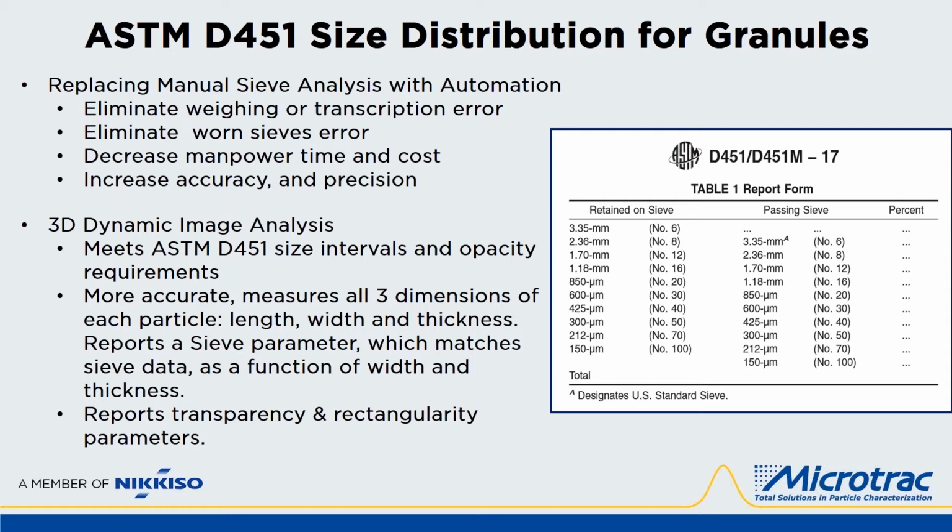Sieve analysis for particle size process control has been replaced by newer automated analysis methods in most applications for a number of good reasons. It eliminates weighing or transcription errors by the operator. It eliminates error from worn sieves, and it greatly decreases the manpower time and cost. It increases accuracy, precision, and reproducibility.